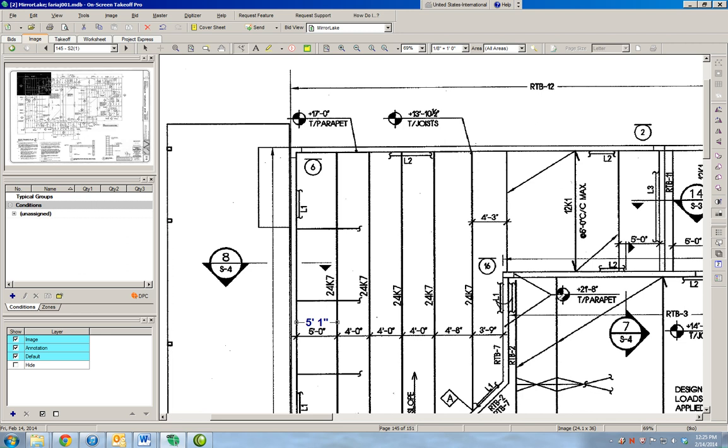So we see wire rope assemblies here, metal joists. These are the ones that we have in our course. We can sort of zoom in here to take a better look. So we see that we have the 20K5, 22K5, 24K6 and 10. So these are the type of joists that we're looking for. And then we look at the units that we have in our table. We have the crew daily output, labor hours, and then the unit. The unit for these are linear feet.